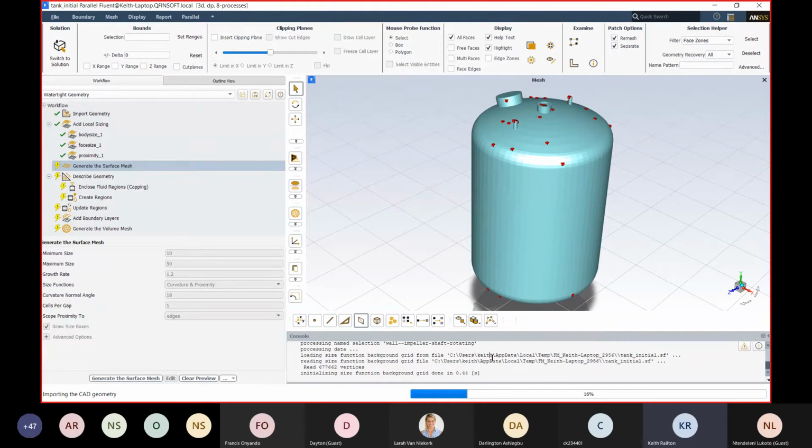Okay, so yes, can CAD designs from other software be used? Yes, it can. They've done a lot of improvements on Fluent so that you can import certain additional CAD into Fluent. So there are options, but it's nice to work through SpaceClaim first to do your cleanup. You could possibly do your cleanup in your other CAD package, but things like creating volumes, fluid volumes and things like that are easiest done in SpaceClaim. It can definitely be done in Fluent Meshing, but it's not the easiest way to do things.